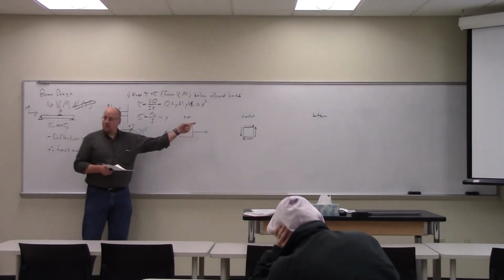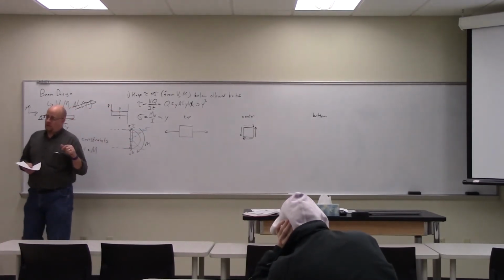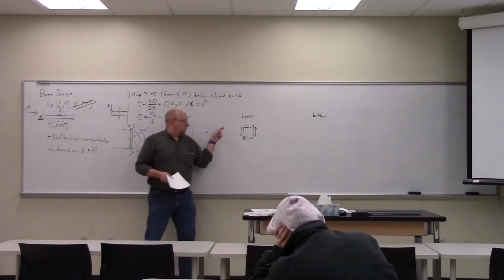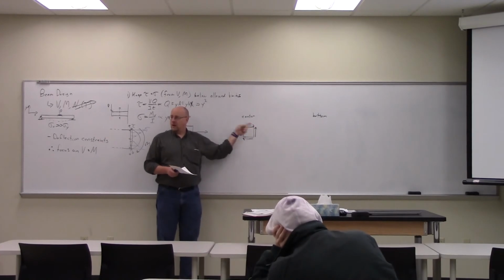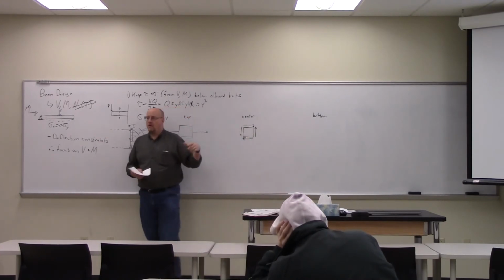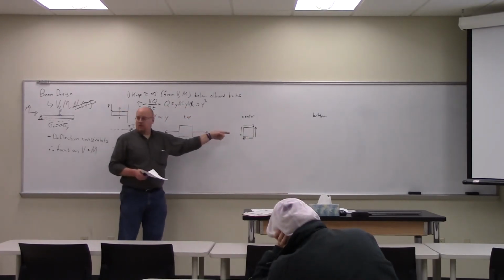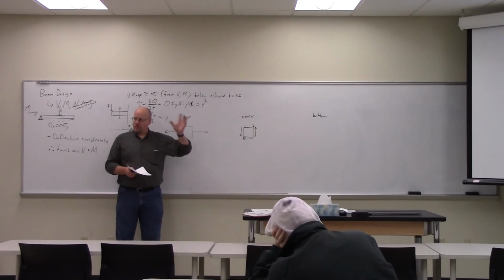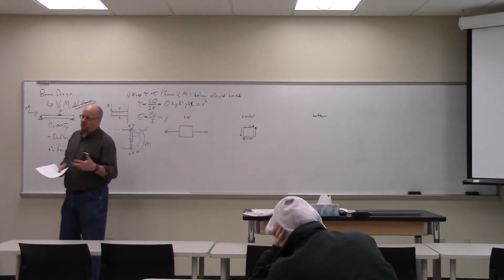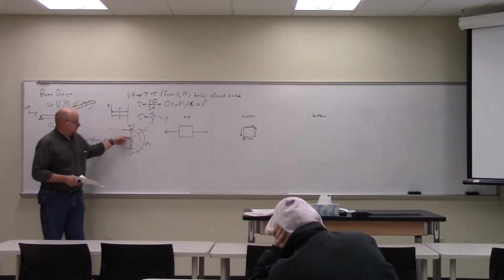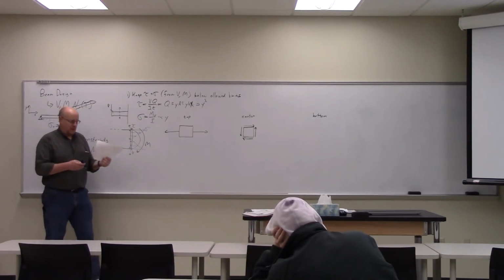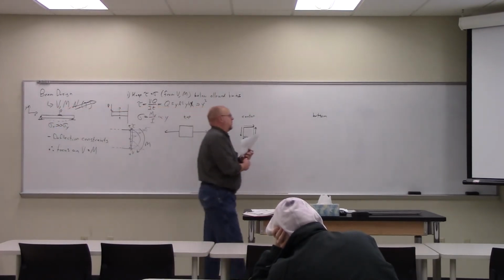So this would be considered a positive shear. In the absolute context of sigma x, sigma y, that's a positive tau xy, but that particular element is being rotated counterclockwise. See what I'm saying? So there are two different contexts. It depends on the context. But anyway, the point is, if you did the force analysis, you'd see it would have to shear like that. Okay, and then what about the bottom? What would the bottom look like?